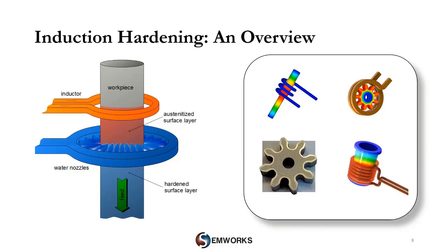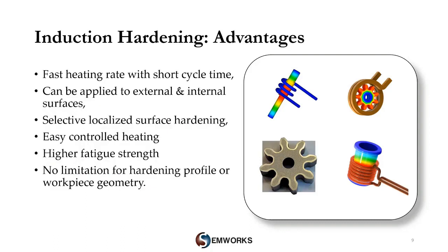There are many types of induction hardening, but they can basically be static or progressive, where we have moving or rotating parts like the inductor or the heated part. This process is characterized by a fast heating rate with a short cycle time.